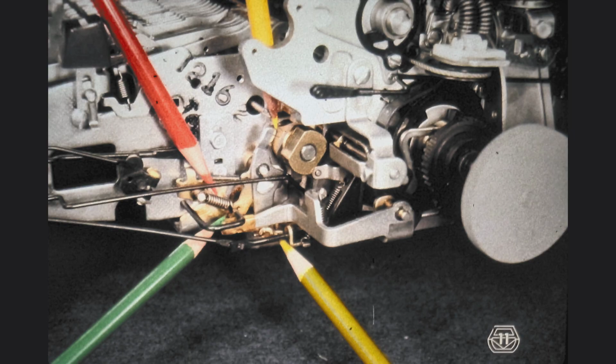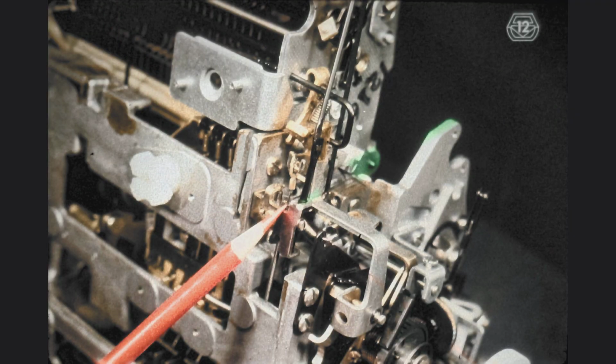Locate, at the point indicated by the green pencil, the portion of the low-velocity actuator which is locked by the low-velocity selector latch. When the low-velocity selector latch is not rotated out of the way of the cam follower or actuator, the amount of motion allowed to the cam follower is very small, as shown by the small clearance indicated by the green pencil. In this photograph, we have half-cycled a low-velocity character and tilted the machine onto its back.